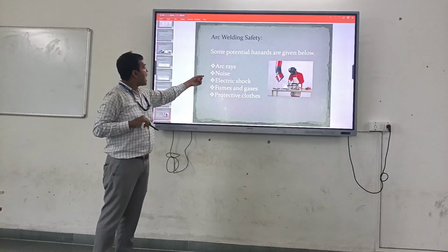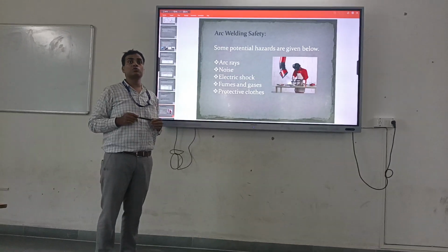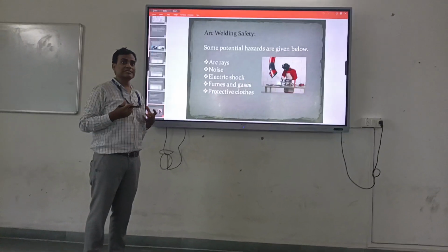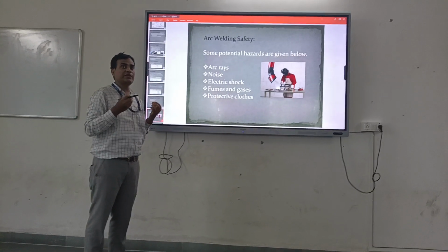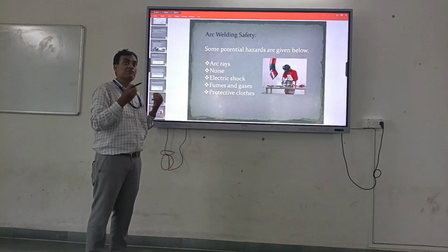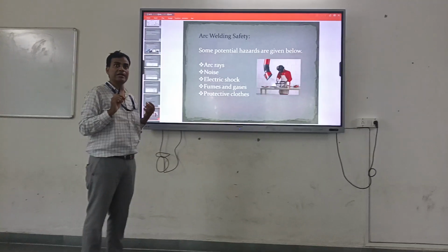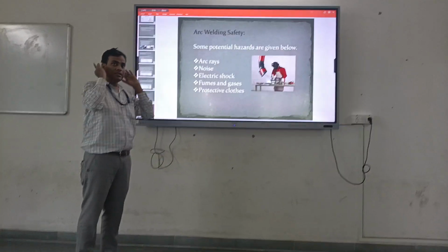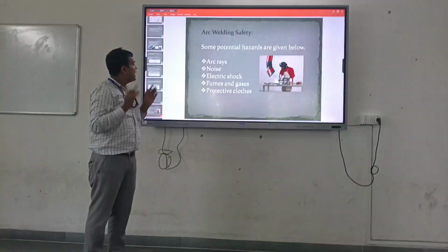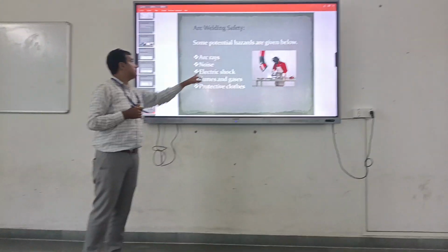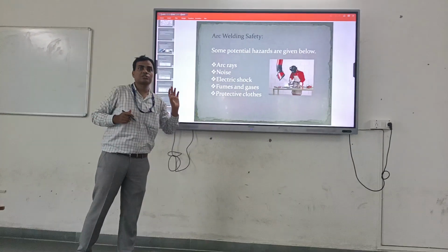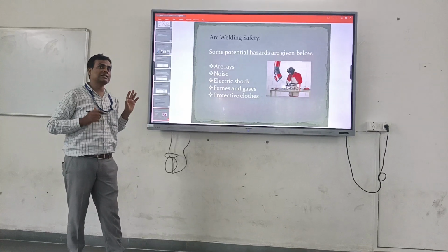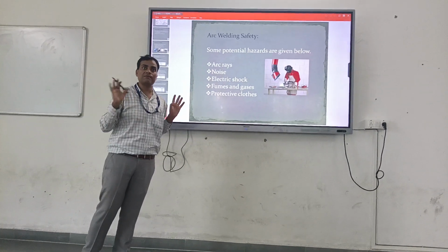So that is arc rays, that is very harmful. So we have to use the sunglasses that are specific for electric arc welding, and also use headphones to protect from the unwanted sound. And electric shock, that is a very dangerous thing. Electric shock directly challenges human life.